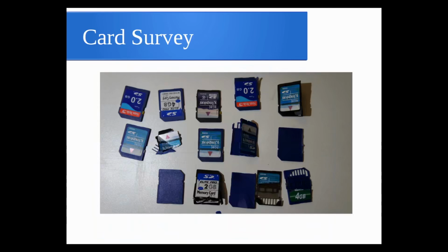Eventually, I got very good at using nothing more than a pair of wire cutters to extract the circuits on the inside of an SD card without damaging them. And you learn all sorts of little things, like how to tell if a card is fake or real, or what the construction of the inside is, by just feeling the card and bending it a little bit.